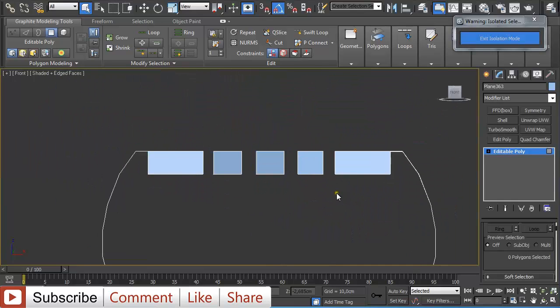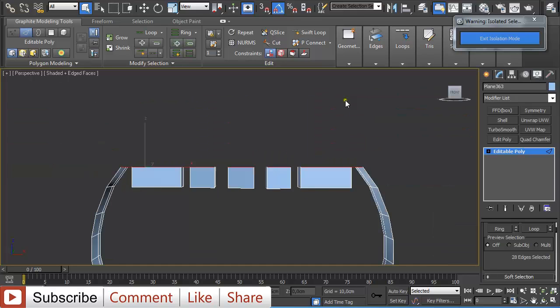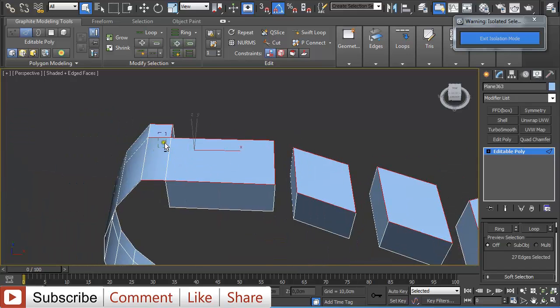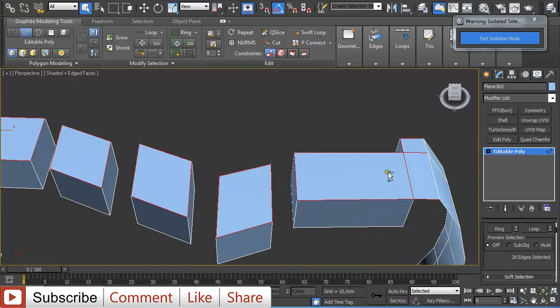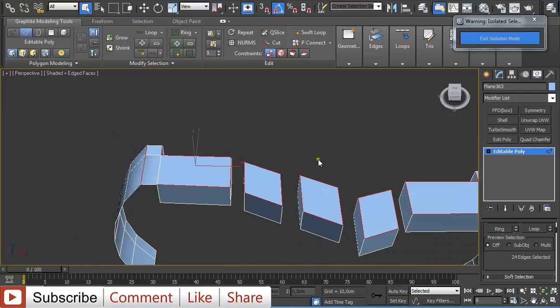So I'm going to go to edge selection and select all these edges, and deselect these ones, maybe select this one and deselect these ones because I don't want to chamfer these edges.